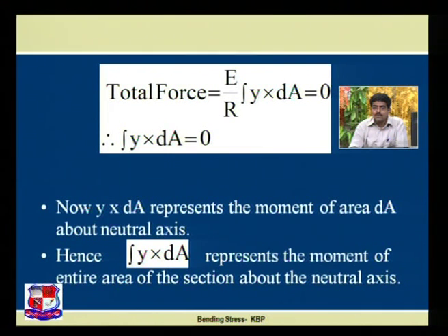What is integration y dA? Let us understand what is y. y is nothing but the perpendicular distance from neutral axis to one specified layer. dA, area of layer, y dA represents the moment of area dA about neutral axis.